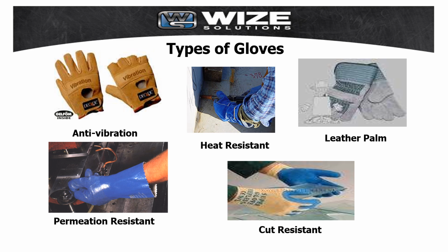Types of chemicals handled, nature of contact, total immersion, splash, etc. Duration of contact, area requiring protection, hand only, forearm, or arm. Grip requirements, dry, wet, oily. Thermal protection, size and comfort. Abrasions, resistance requirements. Gloves made from a wide variety of materials are designed for many types of workplace hazards.